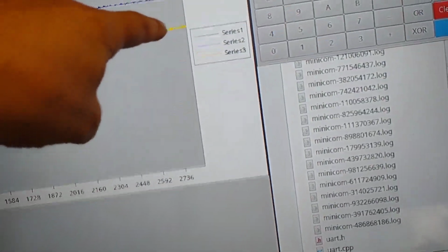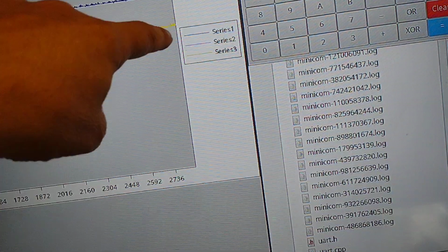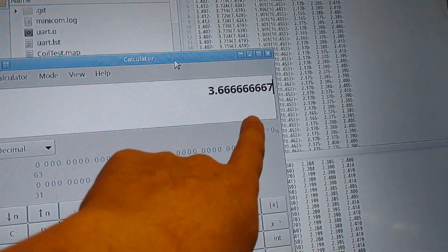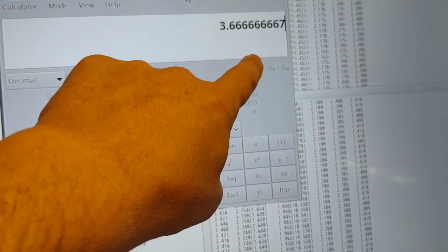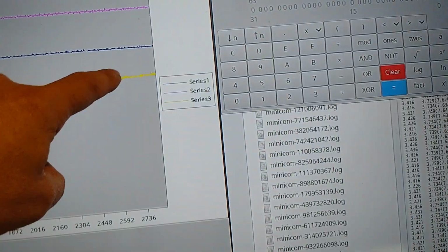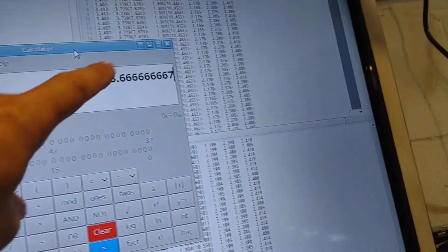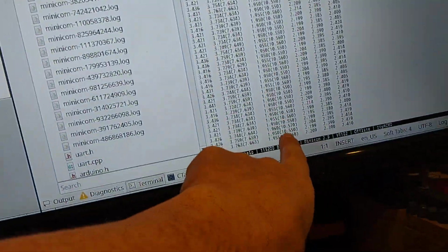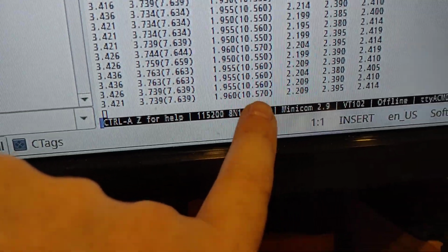Right? So if we were to actually use a battery management circuit, we'd now say, well, this one's low. So charge that until it gets to the average voltage of the pack. Now, the thing is, if you're charging that, then the total voltage of the pack will change because you're going to be discharging it. So you need to recalculate that each time. And of course you can do that because you've got the pack voltage here. That's the actual pack voltage.